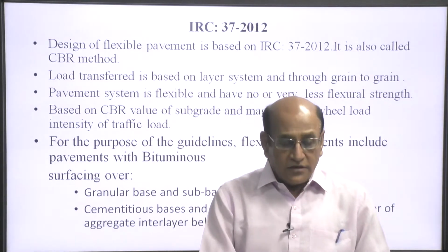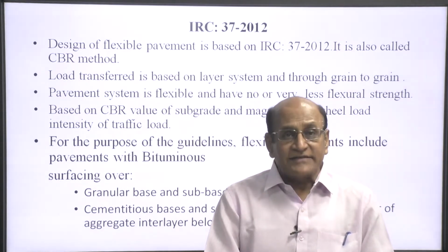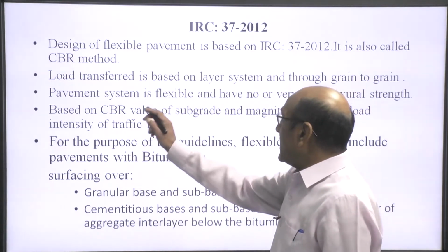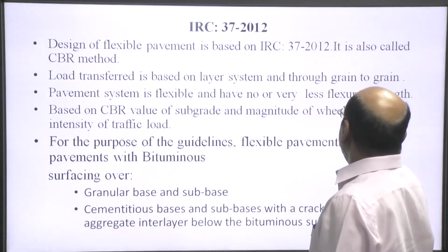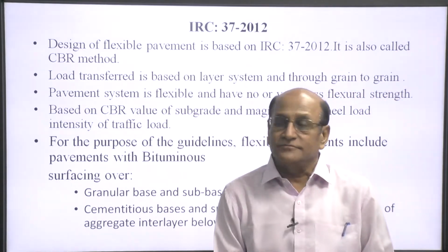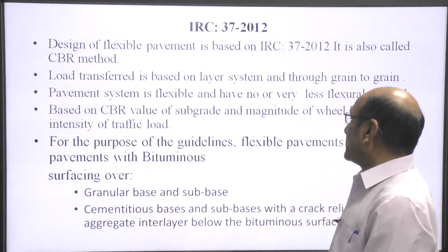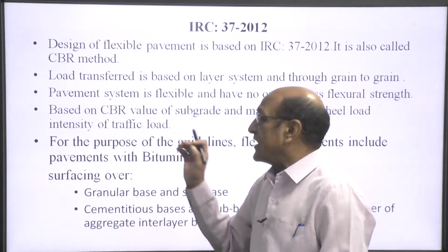Here the load transfer is based on layer system and grain to grain. Pavement system is flexible and has no or very little flexural strength. Design is based on CBR value of subgrade, magnitude of wheel load, and intensity of traffic load.